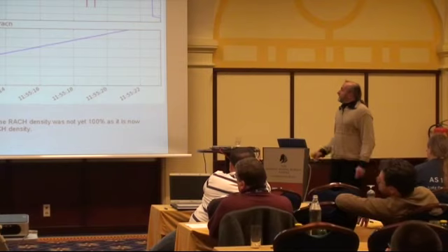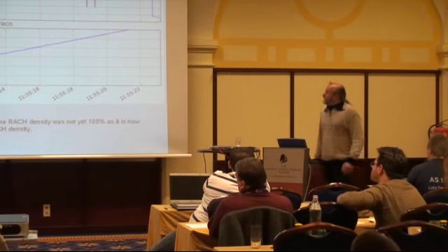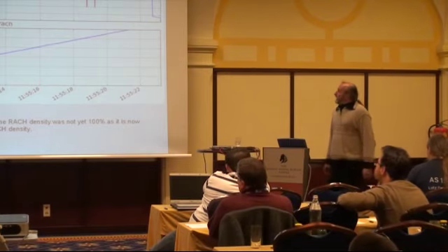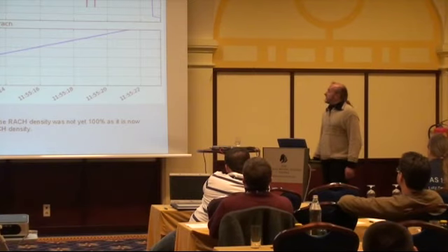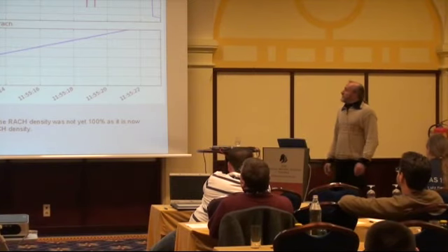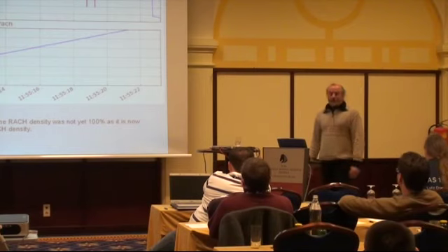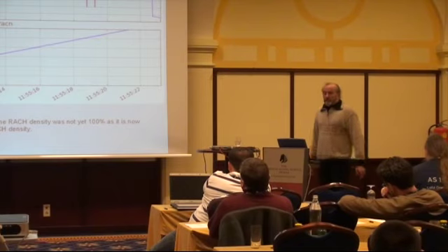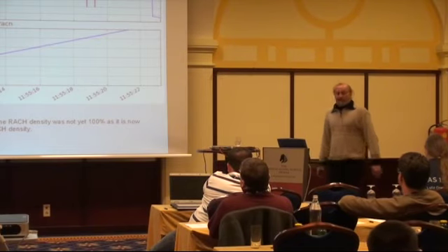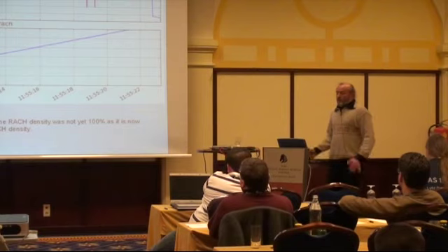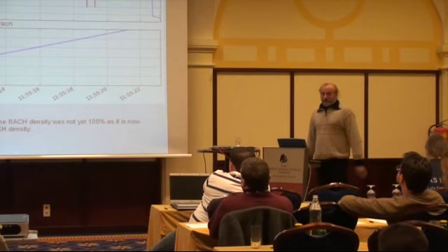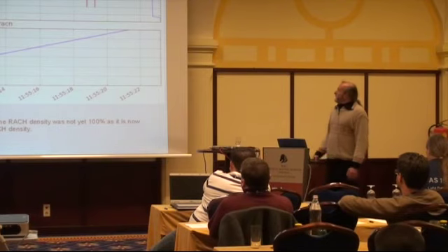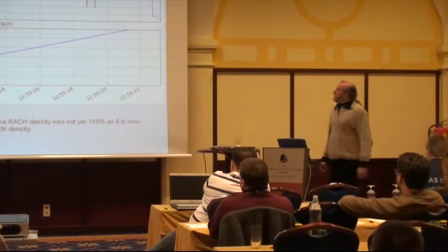In this diagram, I tried to show how it would look with 100% rack density. At the time this measurement was made, the implementation was not as perfect as it is now. Not that perfect means the phone was at that time not able to send a rack burst at every possible slot, but only about every fifth slot of what is possible. So in reality, it would most certainly look like the red lines.